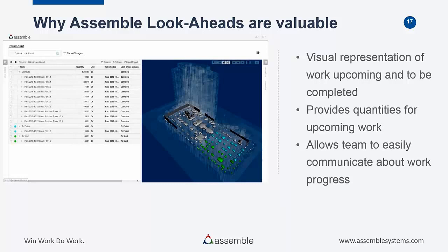What we did is we were able to take our model and basically classify elements and associate them with either work breakdown structure items in the schedule or activity IDs in the schedule. And what this allowed us to do is basically take it out to Excel, compare it to our schedule, and if the date that that element was supposed to start happens in the next 3 weeks, then it would basically say that this item is to start in the next 3 weeks.